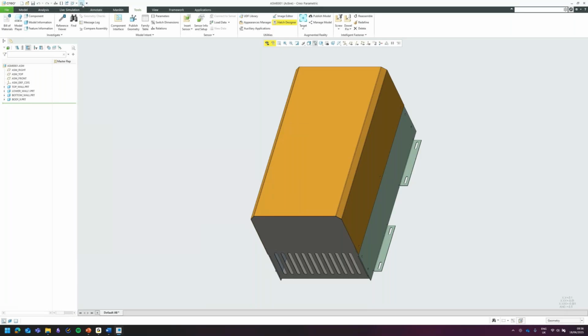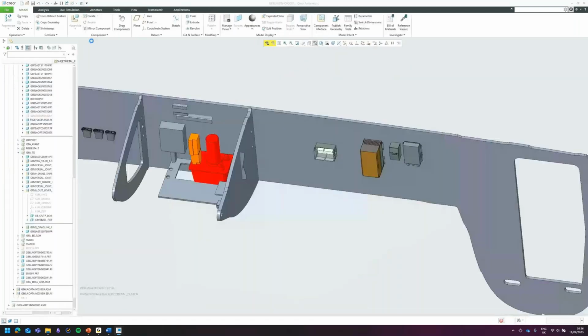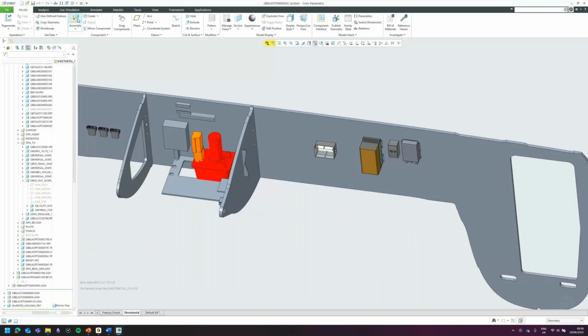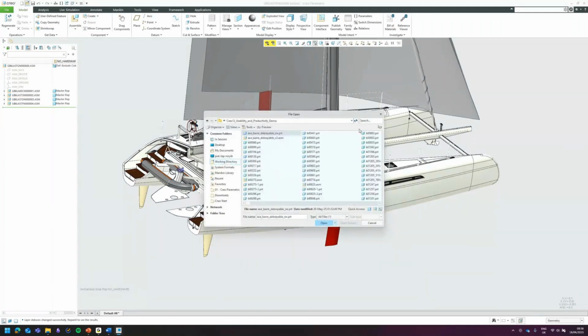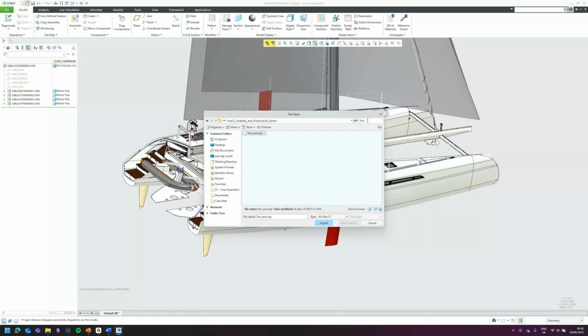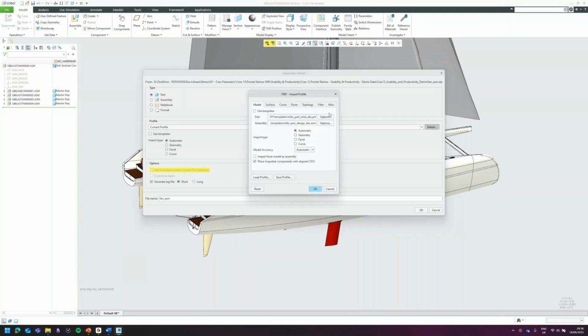Okay, let's close these off. We don't need these anymore, or this one. Let's open a STEP file then. Let's go grab a STEP file. So in here, in my working directory, I've got a STEP file, which if I double click and open this, we can now import as a part. So this is a STEP assembly. We're going to import it as a part. Just need to make sure under topology, we're maintaining the multi-body structure for assemblies.